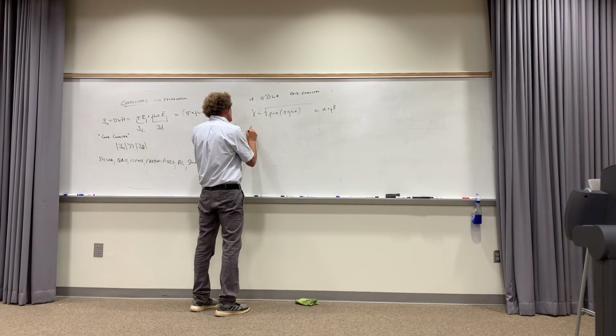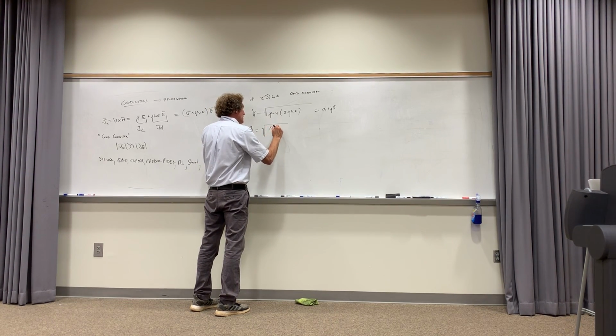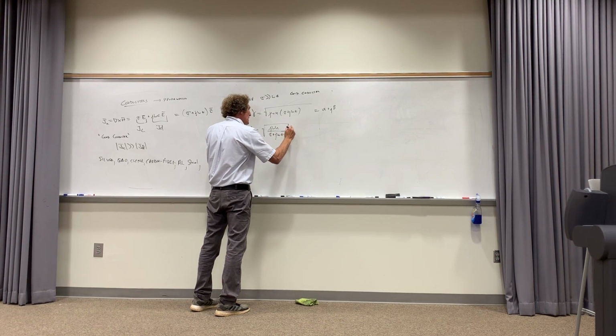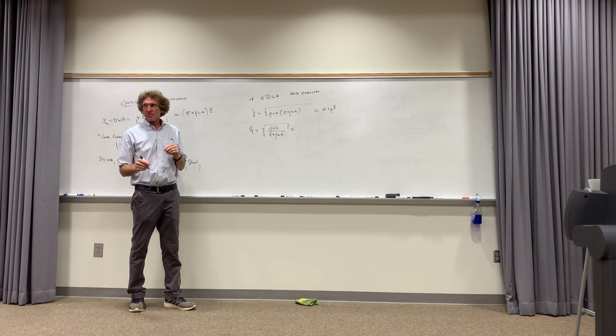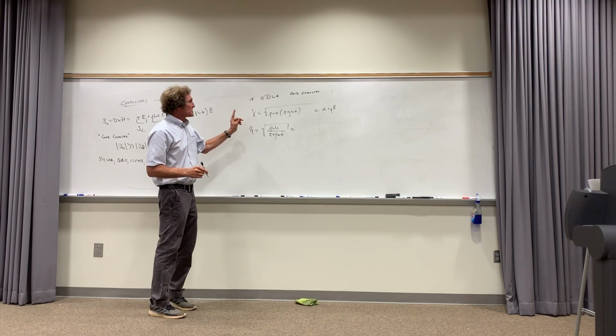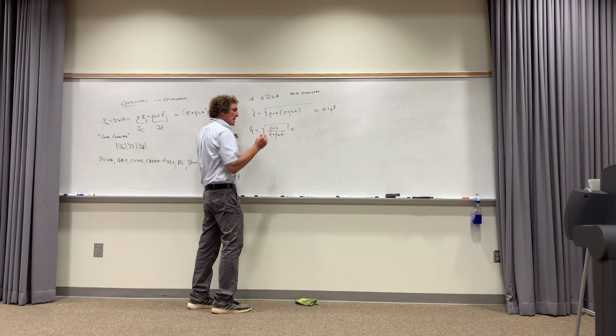But there's also the intrinsic impedance of the media, and that's the square root of J omega mu over sigma plus J omega epsilon. Right? Now please watch this. This is important. You're going to get tested on this in quizzes and everything. So keep watching this. Now if it is a good conductor, that means sigma is much, much greater than omega epsilon, right?